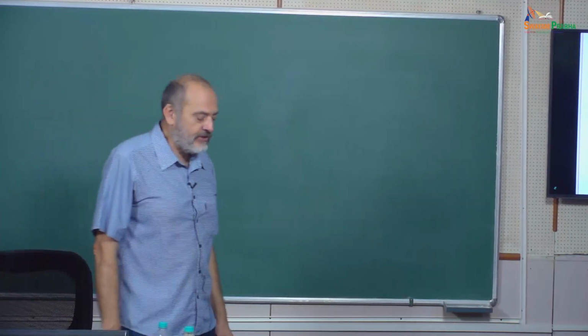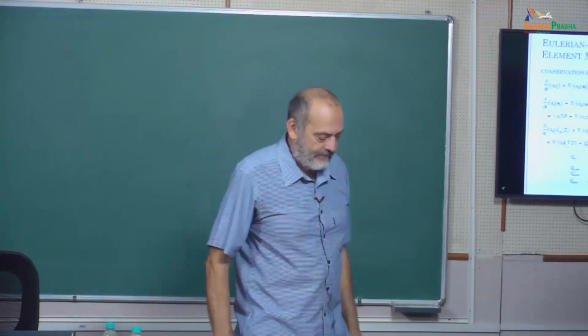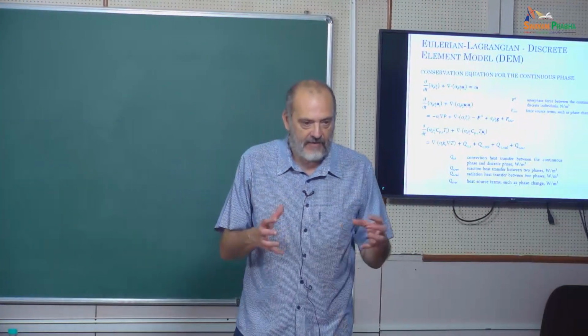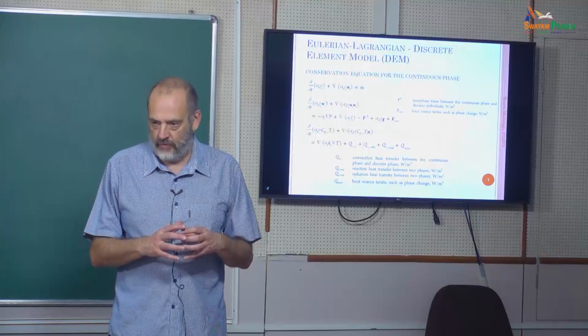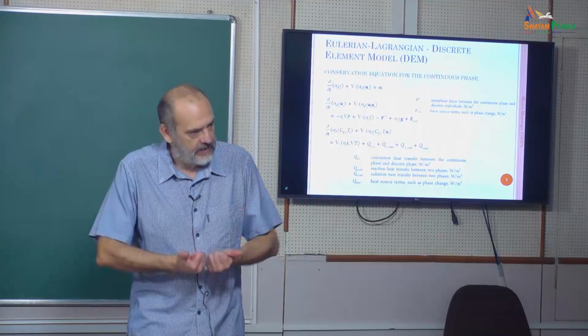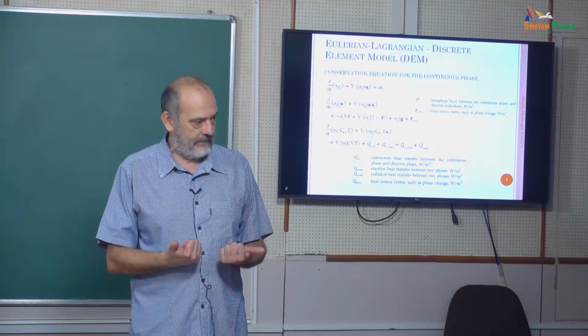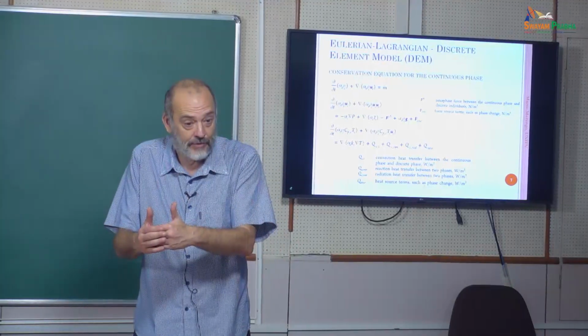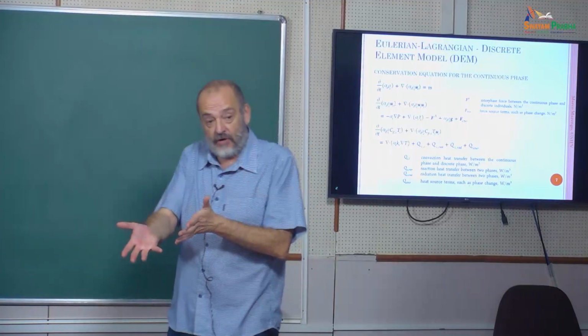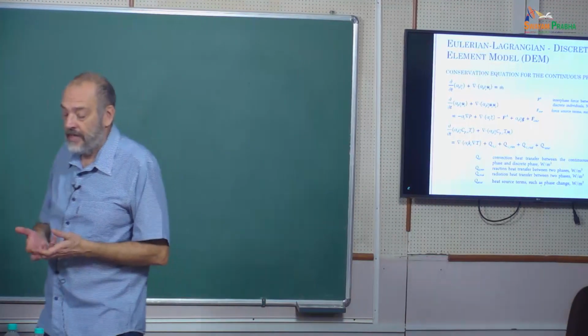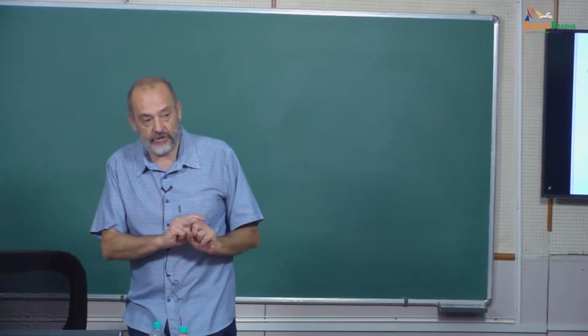Imagine that we have a droplet that is evaporating very fast. So we have a flow, the so-called Stefan flow, from the droplet that is producing vapor that is going outside. But this is giving pressure because every time that we have a motion, there is a pressure. Right? So this is a force, and we need to include this force, which is related to the phase change.